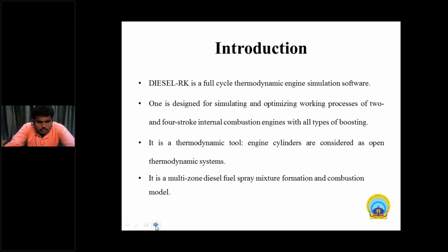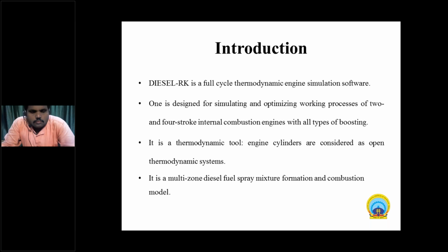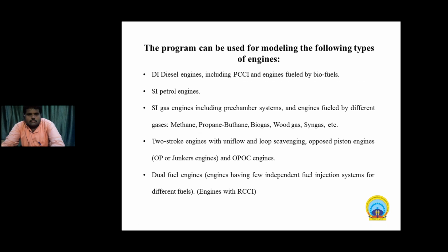The combustion model includes the self-ignition delay calculation sub-model based on the detailed chemistry simulation of methanol pre-combustion reactions, a sub-model of evaporation of methanol droplets, and sub-models of the methanol fuel spray penetration. Then there is the spray angle also, and the droplet forming. So these are mainly what we are focusing on when we are doing this Diesel-RK.